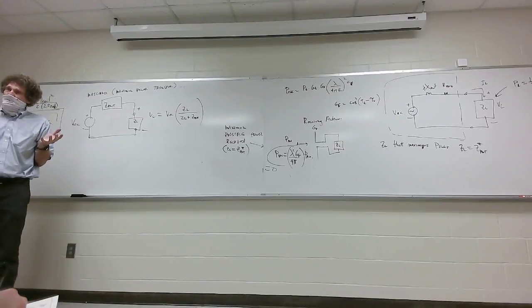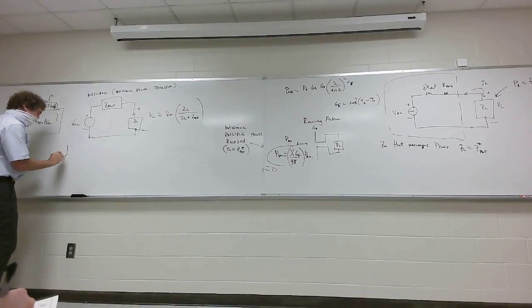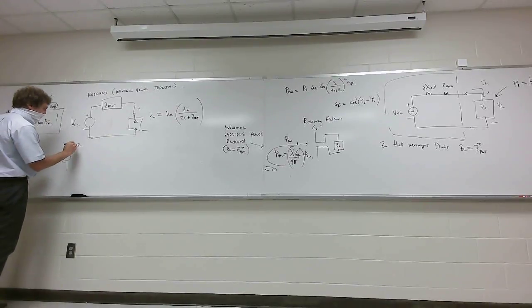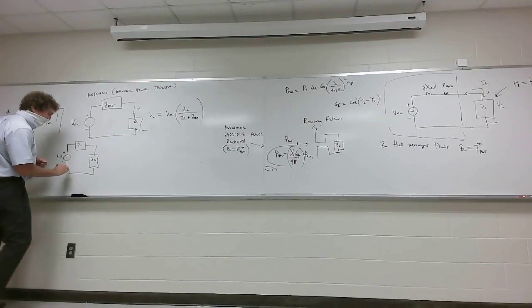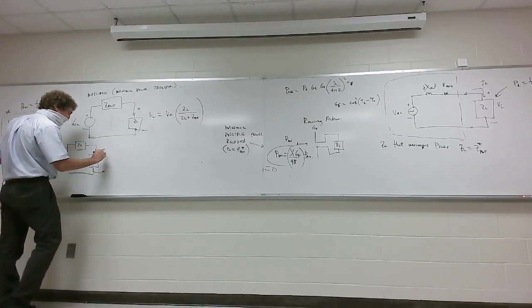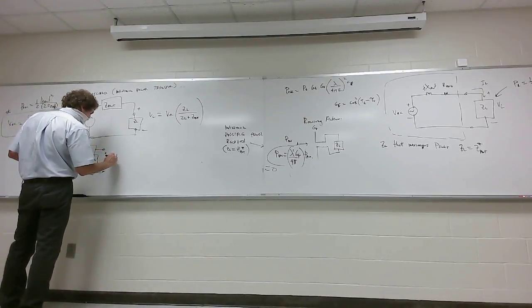Think about it. Isn't that just voltage division? I could make it real and say, if this is plus or minus 10 volts, and this is 20 ohms, and say the load is 30, and I want this voltage here, that's just going to be 10, right?